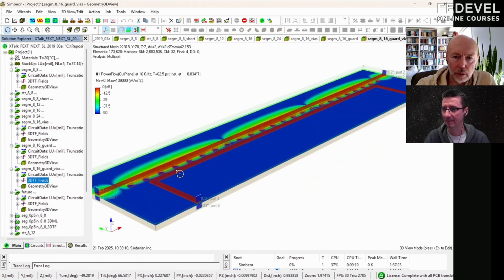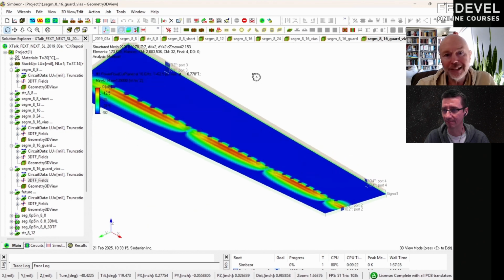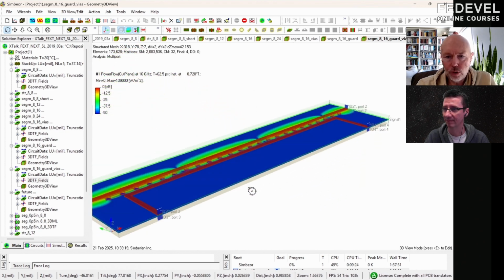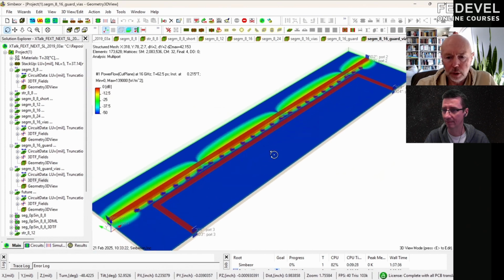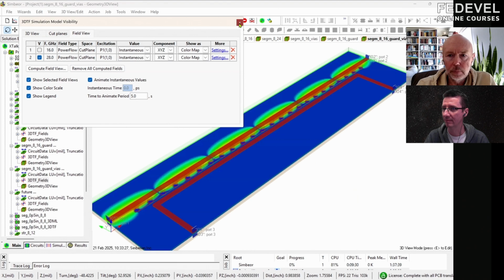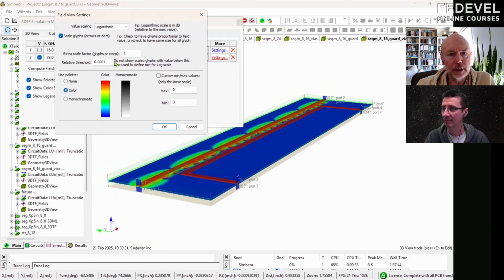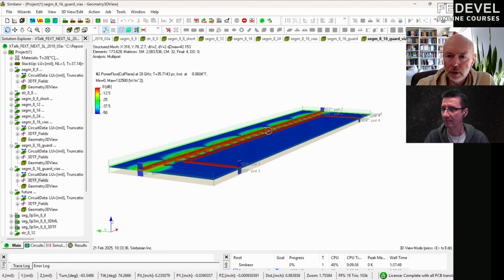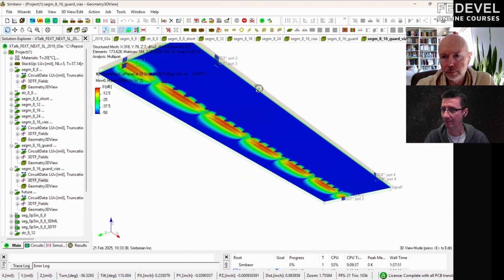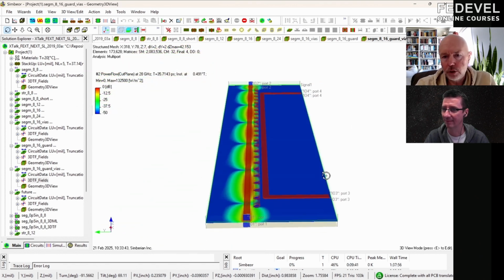Like this. And we see that the level of minus 50 dB here, I put minus 50 intentionally, no crosstalk at 16 gigahertz. At 28, we will probably get some. No, it's minus 40. Let's just recalibrate it to minus 50. Again, put one more zero. And it's still nothing. So this thing actually works.